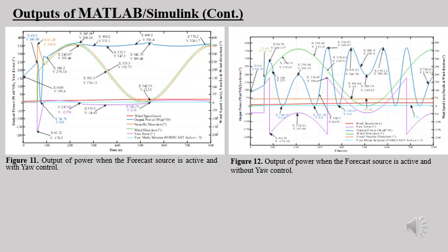Later at 355 seconds, the system remains within the plus or minus 15 degree dead band, still generating 3.47 kilowatts. Throughout the simulation, power rises to about 3.5 to 3.6 kilowatts during close alignment and drops when the forecast shifts away. Overall, even when both primary inputs fail, the forecast based yaw control system still maintains reasonable tracking and stable power.